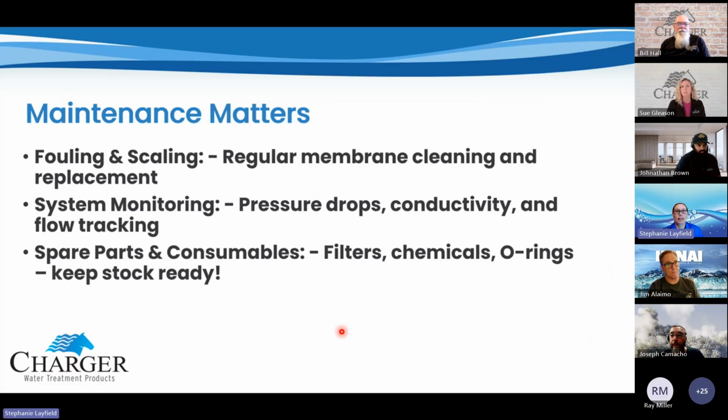Maintenance, just like our residential ones, maintain it. That's going to be regular. Whenever you try to push that really far is when you can get burnt by it. When we're talking about the whole home with scale, that's not too much of a critical thing. But if we're looking at a commercial application for a distillery and we have chlorine hit through the activated carbon onto that membrane and it burns through it, then we have a larger issue. So make sure we do regular cleaning or replacement.